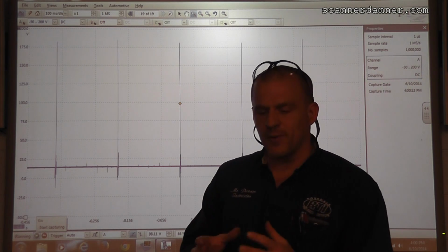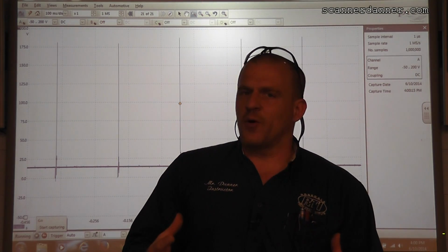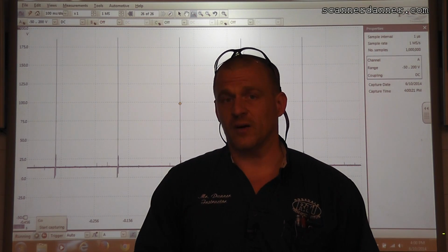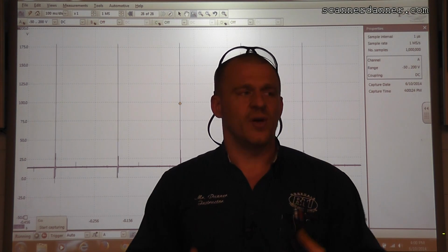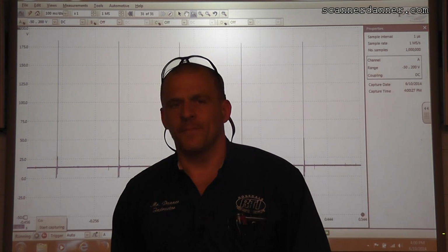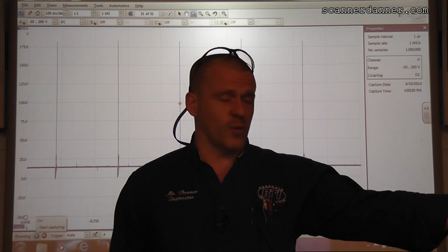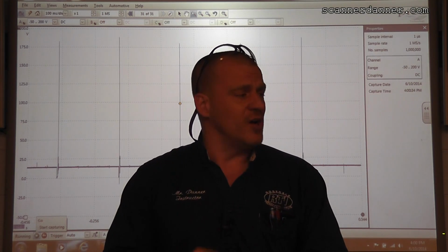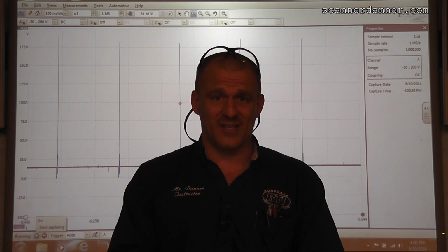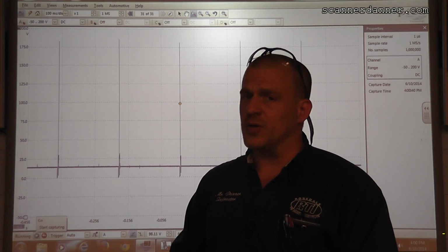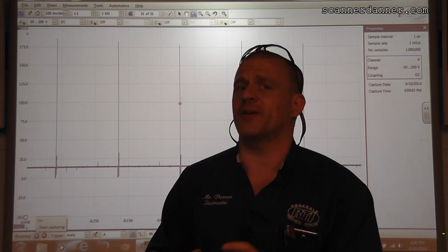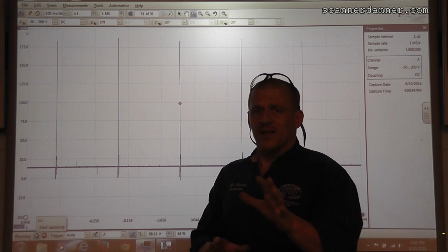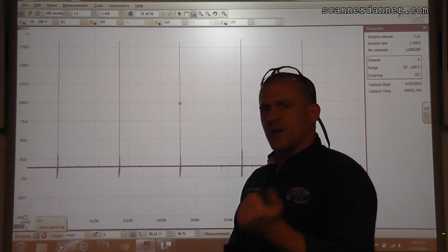I always tell my students what we want to have is the best of both worlds. We want to see repetition and we want to see detail. But we don't want to sacrifice detail for that repetition. So looking, especially in an ignition firing event like we're looking at here, there's going to be times maybe where that signal's dropping out and I'm getting a misfire, or maybe we're doing some snap throttle tests and we want to catch that. We need to know how to use our sample rate, our time base, our buffer to be able to catch those events. I think I can simulate that for you, but I think I'm missing one point before I show you that.